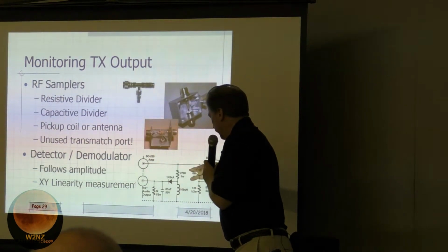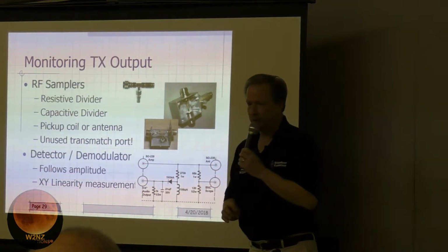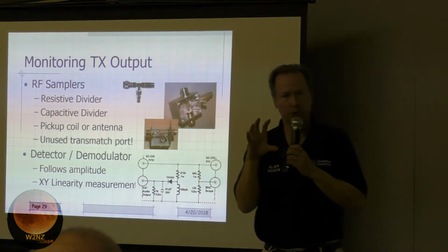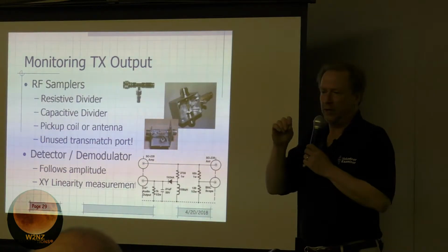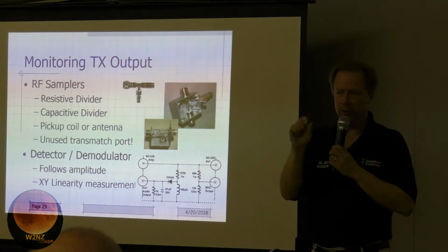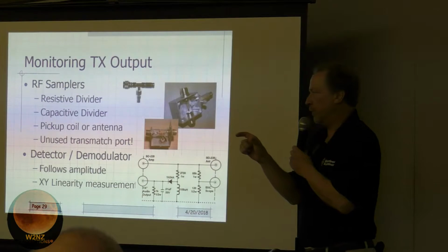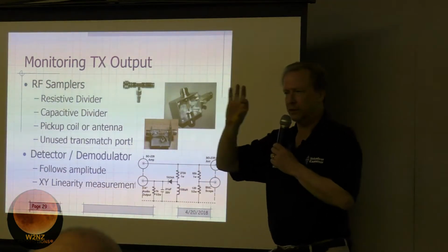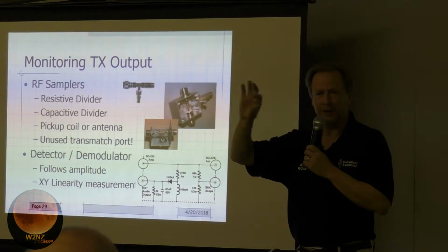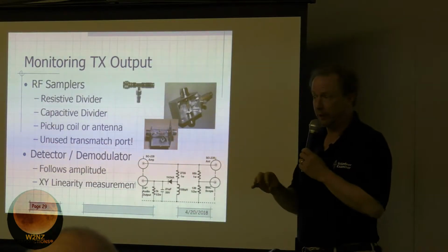These same two connections, if you built them separately, can actually be used to do a trapezoidal measurement, where you actually have X being driven by the audio signal and Y being driven by the output of your amplifier. And you'd ideally get these nice Christmas tree shaped responses when you've got a nice linear amplifier.